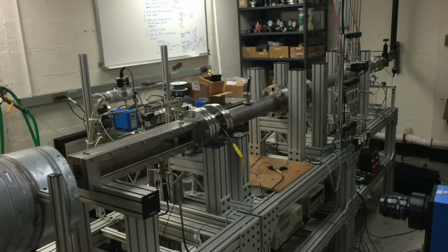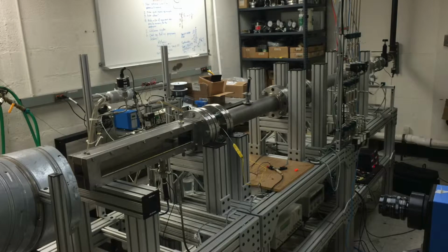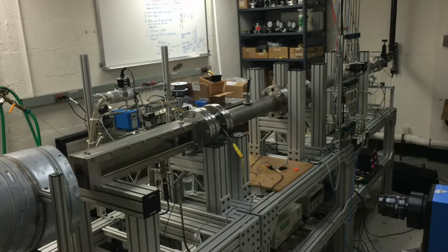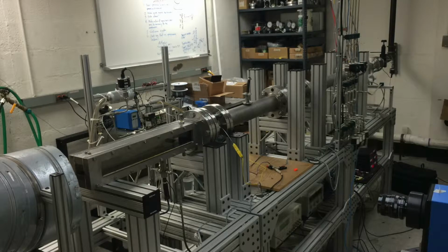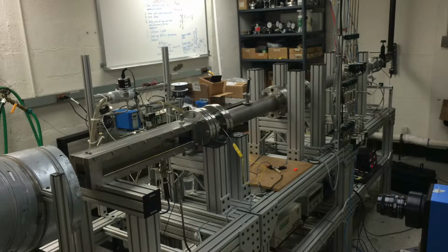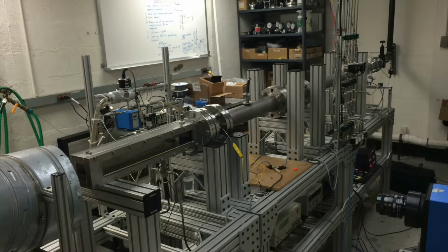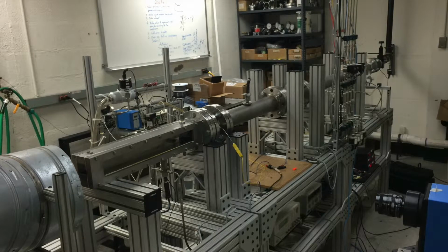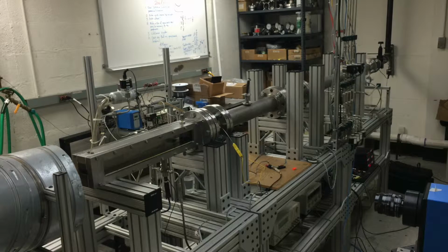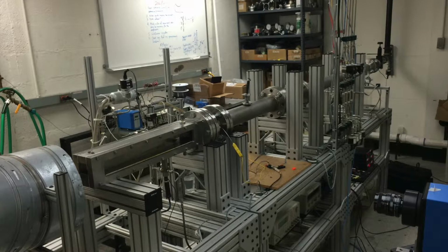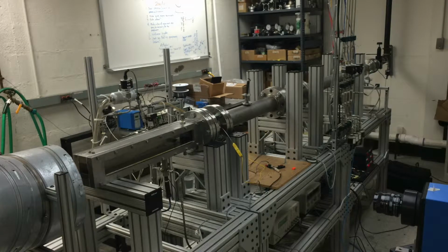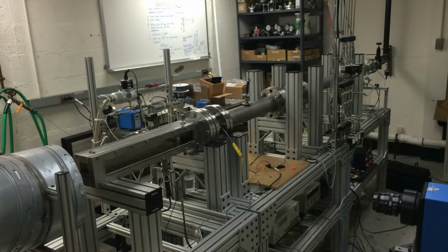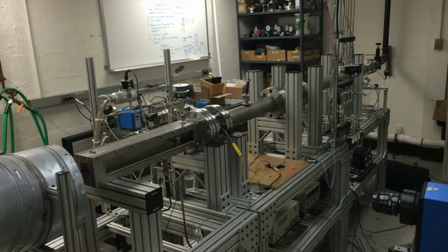The problem of interest in this lab is to look for combustion instability modes in such afterburners and to find blow-off and flammability limits for various flow speeds and equivalence ratios. In this lab, we will look at some important combustion characteristics of a jet engine afterburner. Primarily, we will be interested in finding the flammability and blow-off limits for the afterburner for a given flow speed through the engine and primary combustor equivalence ratio.